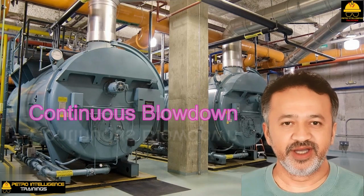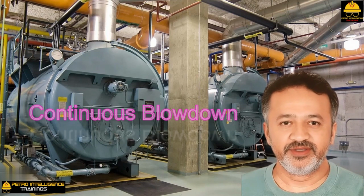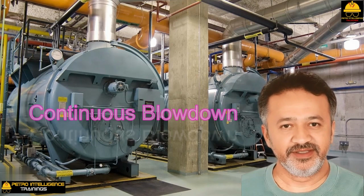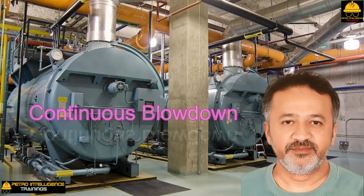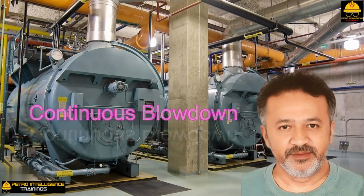The correct drain location is somewhat below the minimum water level in the boiler steam drum or in the kettle-type boiler. TDS in the blowdown is based on what the steam will be used for. A typical value is 1,500 ppm.